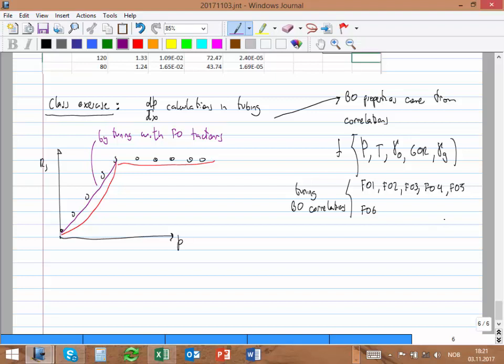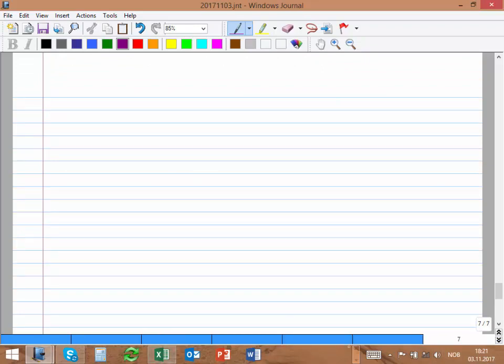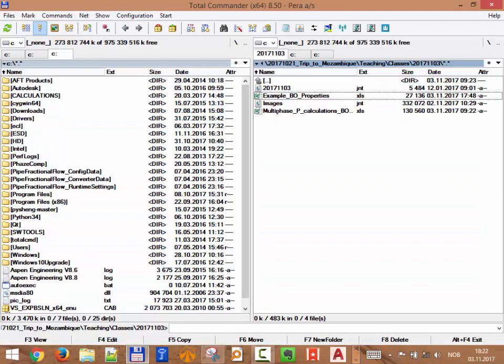And we're going to the part, in this calculation, where P wellhead pressure is known, and I want to calculate P bottom hole pressure for a rate of oil equal to 1,000 standard barrels per day. And actually, these correlations are in field units, so we are going to have to change, because all the rest is in metric, okay, all the pressure drop calculations. It will be a bit tricky to do. But let's go and show you the exercise, and that's the last exercise of the course and the last activity we have for today.